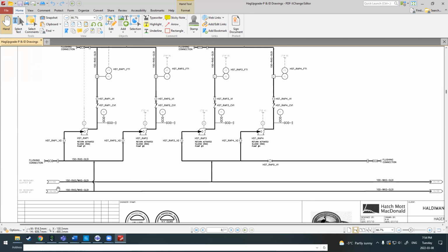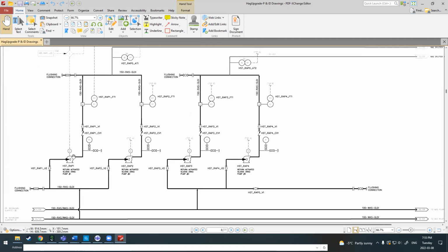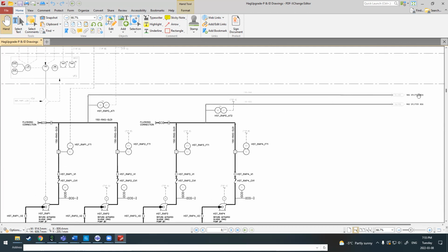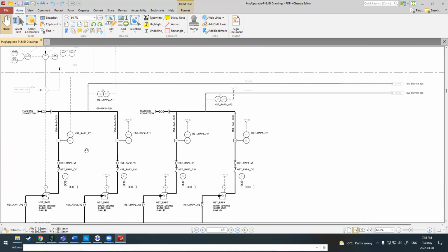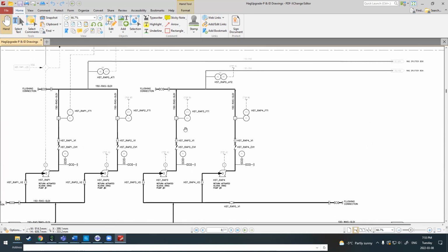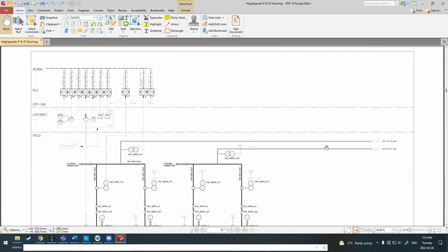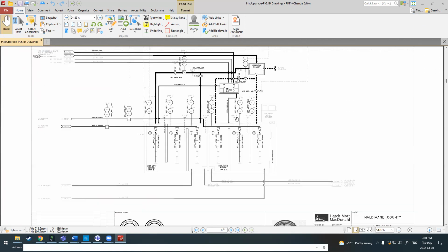So you really need to watch for the process arrows. You can see that this is a sludge line from clarifier 2. This is one from clarifier 1. So the sludge line is here. These return activated sludge pumps will then draw sludge up through, push through these check valves, flow meters, and then they'll push them out here to the ROS splitter box, which is what we saw before. So we can see that this drawing, these pumps would then feed into, and then to trace those lines, you have to jump back to this drawing.